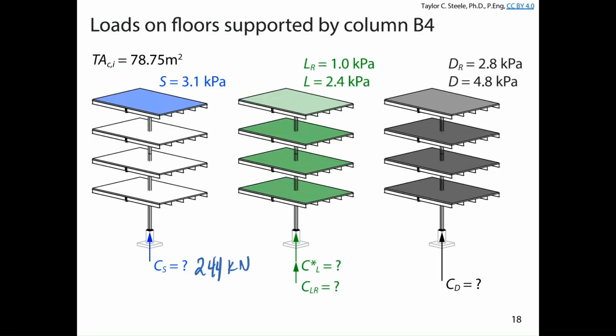Have any questions about that? That's the simplest calculation we're going to do. Okay. Next, we're going to look at the live loads. And again, like I said previously, we're going to separate the live loads out by occupancy. We've got office space live load, minimum roof live load. We're going to look at those as 2 separate actions because they get treated differently when we start to add stuff together. And some of them can be reduced while others cannot.